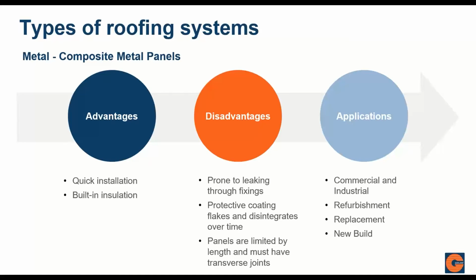time. But when we come to disadvantages, this is very similar to the previous slide. If we haven't got the correct fixings or they're not torqued up to the correct specification, you are prone to exposing leaks. So we always recommend that you follow manufacturer's details and specifications of fixings. Again, the coating can come off, which I won't cover again.